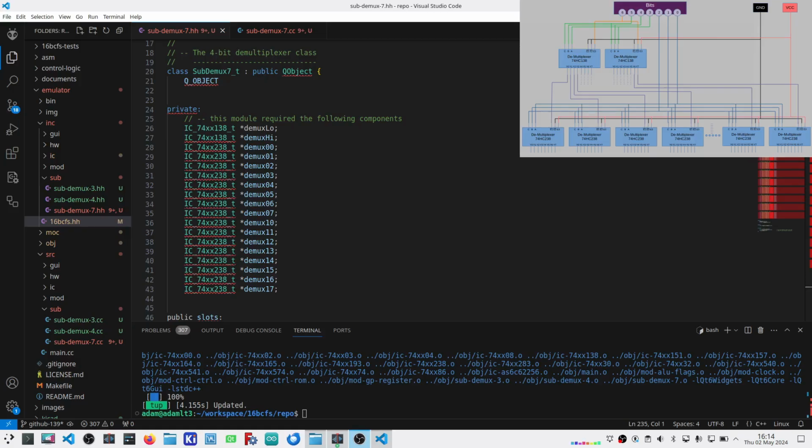Okay, the 7-bit demultiplexer is actually more of the same, but on steroids. Up here at the top, I have a 4-bit demultiplexer, and I've built these using 74HC138s rather than the 238s that are going to drive the final output signals. Now, why would I do that? Well, it turns out that the 138s are slightly less expensive than the 238s, and if I can save a buck or two, I'm going to save a buck or two.